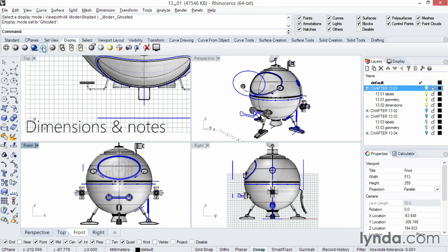So you probably remember me talking about never ever deleting curves. This is going to be a great example of why you shouldn't. We're going to need these curves to snap for our dimensioning. I'm going to go down to the O snaps here, and I've selected most of these. You don't need them all, but some of the basics are point, mid, center, intersection, and probably quadrant. We have a lot of curves that'll really help.